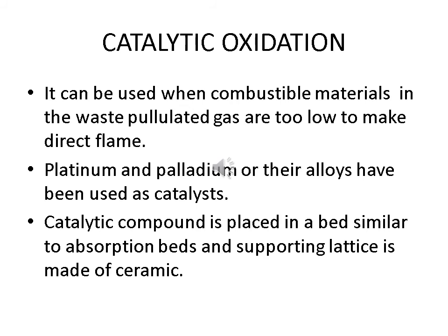These catalysts are placed similar to the absorption bed. That means they are arranged in such a way as to provide the maximum possible surface area for contact with the gas. This catalyst is coated onto suitable elements such as metal ribbons, ceramic rods, or alumina pellets. That's known as a supporting lattice. These elements are then packed into the catalyst bed. You can see the figure in the next slide.